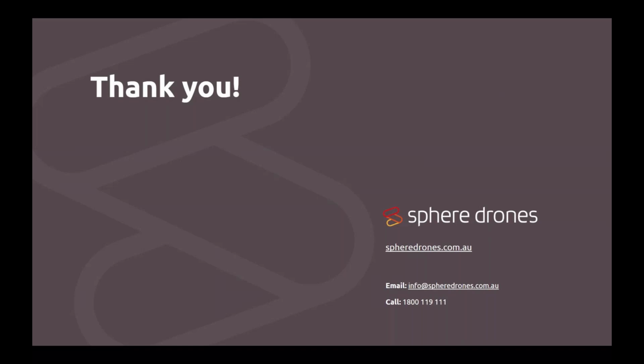What is the quality difference between the Mavic 3 Enterprise versus the Matrice 350 RTK with respect to photogrammetry data? Thanks for the question, Andrew. The short answer is that as a solution, they both are very high quality, and I think it ultimately comes down to the workflow and what you need or want to do, what sort of area you want to cover, and whether you have any requirements for licensing and certification. One of the beautiful things about the Mavic 3 Enterprise series is that it is in that sub 2 kilo category, so you can operate that unit under an excluded category certification.